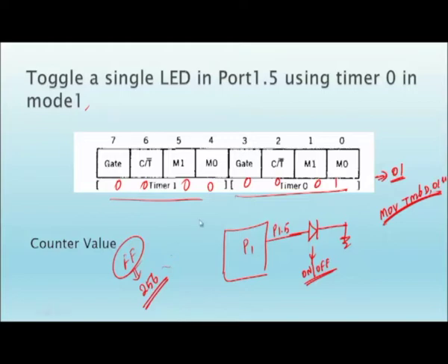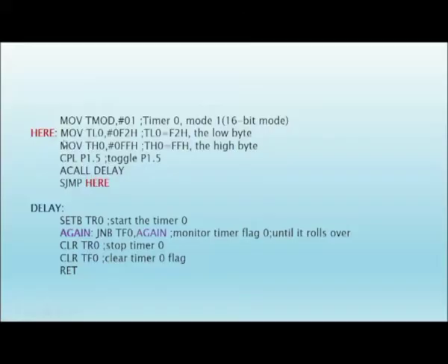We will explain here. Now, take this program for toggling the LED. We already calculated the TMOD value: MOV TMOD, #01H. What it indicates is that timer 0 is initialized in mode 1. Here we are starting with a 16 bit mode value. So, my required value was